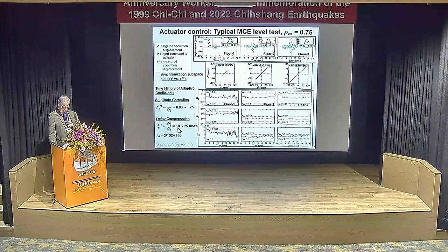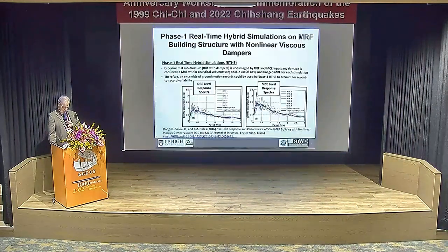If you say, well, okay, 18 milliseconds is pretty small, right? 35, but look at the time step, that's only 3. If we didn't correct it, we wouldn't have made it through the earthquake because you're going to put energy in the system and it's just going to blow up on you.